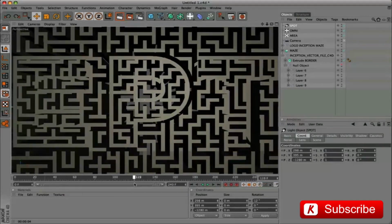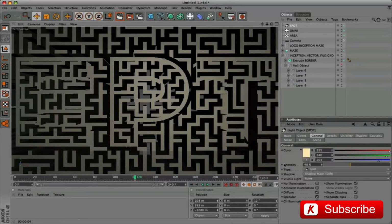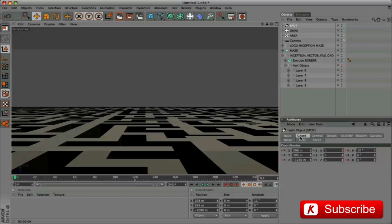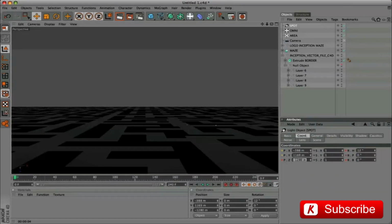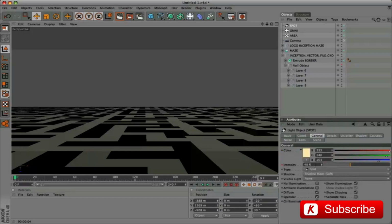Go to frame 120, activate the coordinates keyframes for position and the intensity keyframe. Go to frame 0 and insert the values x minus 388, y 1169, z minus 928, rotation minus 29, minus 36, 30. Activate. We bring intensity to 70.